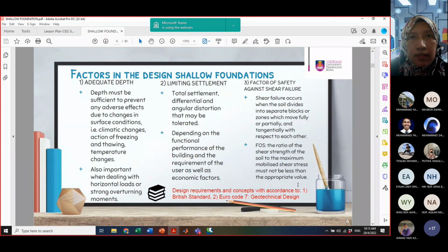In whatever geotechnical design application, you have to meet the design FOS number. For example, for slope stability applications there is a standard FOS that you must meet, such as a stable slope needing to be equal to or more than 1.